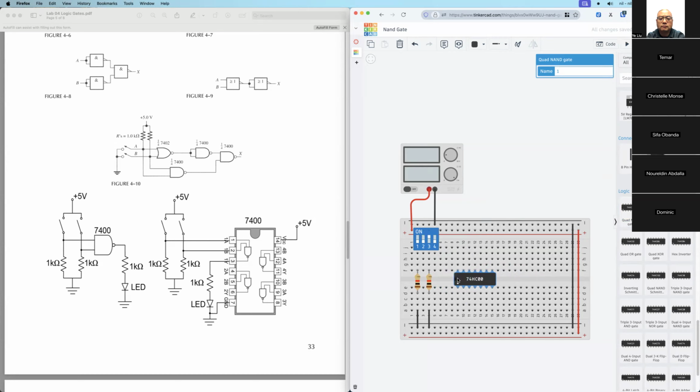This is get the direction. So this is the pin 1, then 2, 3, like this. So this is 7, should go to ground. Then 14 is this, so connect to the power, positive 1. So connect, change this to right.